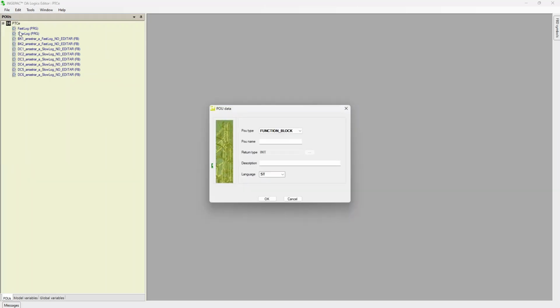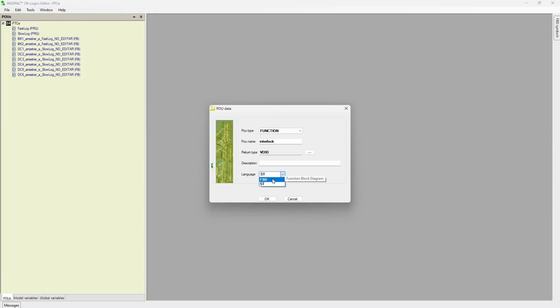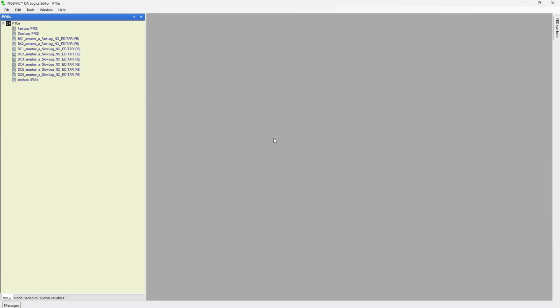Prior to beginning with the code, the POU type, name, and programming language need to be selected. In this case, a function type POU will be implemented with the FBD language. Functions are usually implemented with a function return, the result reflecting the execution of the code, which may be of the following data types. However, no function return will be used for this example. Lastly, the FBD language option will be selected for this example.